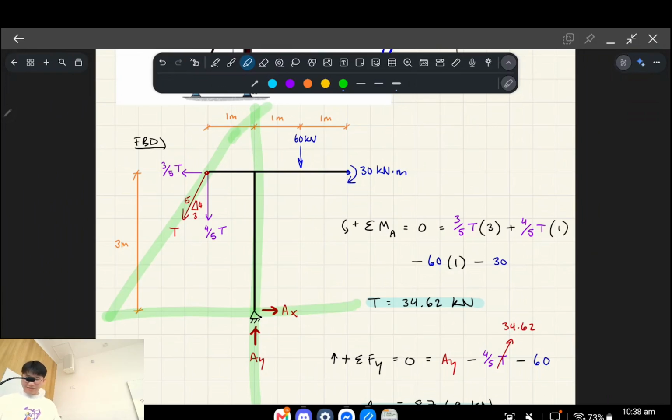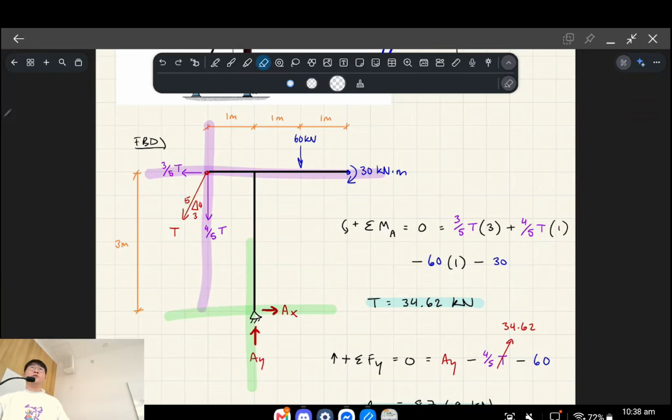Do you see how if I pick the point A, we can actually solve this? Because we're left with one unknown, which is the tension T. But if I decided to split that unknown into its vertical and horizontal components, then if we picked point A, on paper we've actually got two unknowns now. We've made more unknowns and more problems for ourselves, on paper. But the reality is that when you do this, you can still solve it.